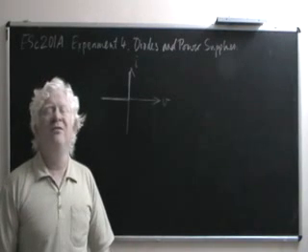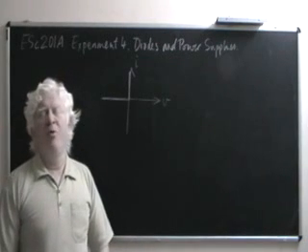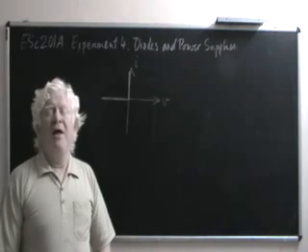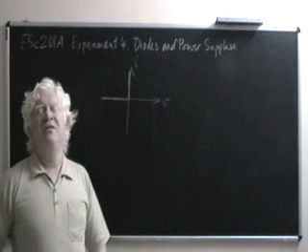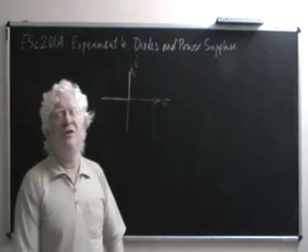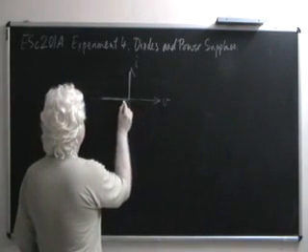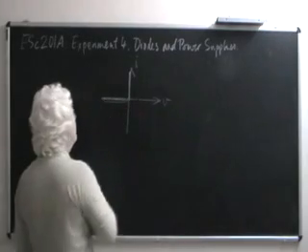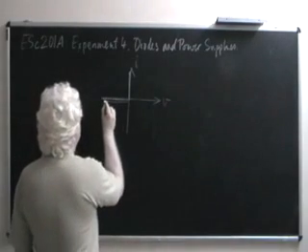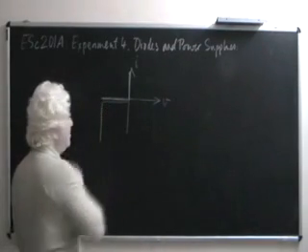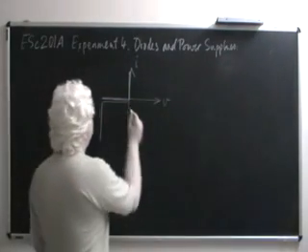But that happens only once in its lifetime, for the last part of its life. So we are never supposed to apply a very large reverse voltage to the diode. Whatever voltage we apply should be within what is called the peak inverse voltage rating of the diode. So let's look at the reverse characteristic first. Something of this kind, until it breaks down. And the breakdown phenomenon would look like this. So you see, when reverse voltages are applied, there is a very minor current.